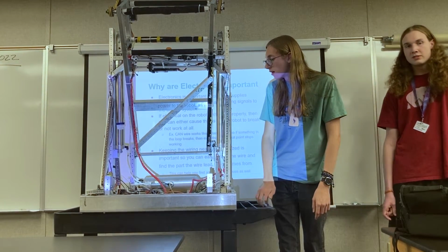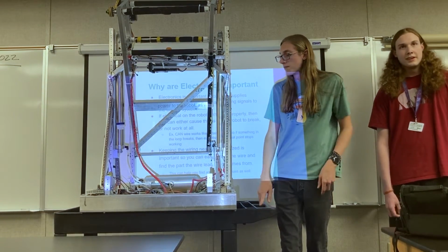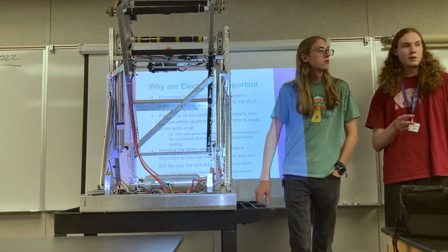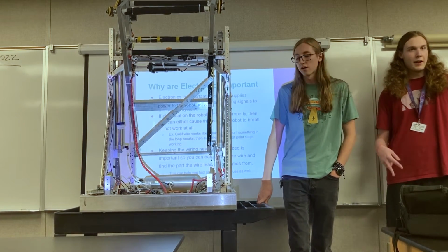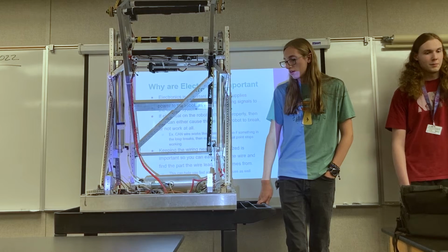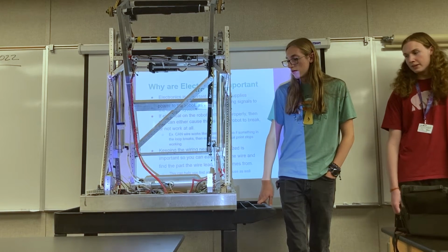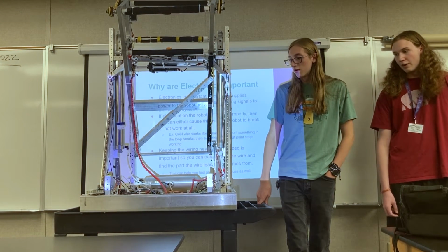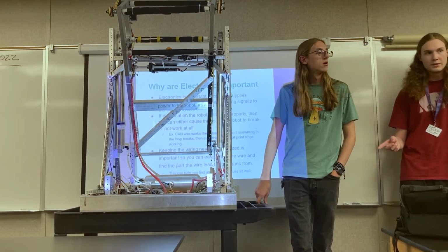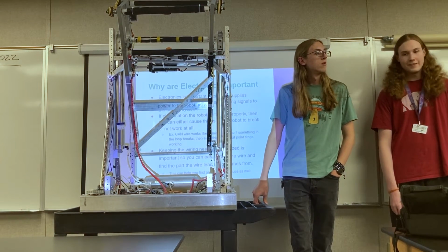Because it's also a lot easier to code, because with CAN you have to determine where the loop is, and if the loop breaks, then the whole thing breaks. Everything past that point in the CAN will break as well. So PWM just seems to work a lot better. But they are more expensive motor controllers, which is why our first year we didn't have them.